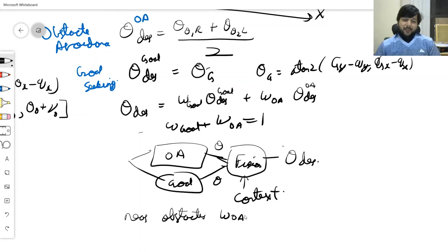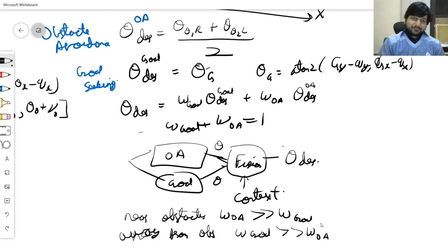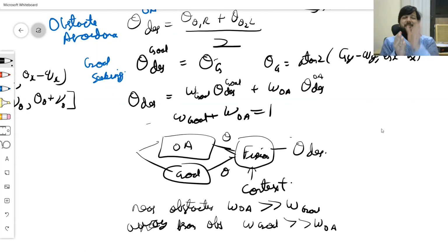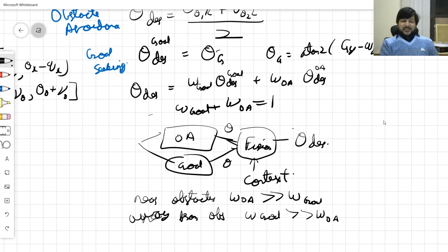I am more obstacle conscious, and away from obstacles, I am more towards go straight to the goal. So that's a fusion, and again, fusion you need to take care of. Sometimes two opposing behaviors, avoid this obstacle from the left, avoid this obstacle from the right, and you bang into the obstacle. Weighted addition. That's why as we go nearer to the obstacle, the goal will be gone, and first avoid the obstacle, we'll care about the goal later. So that's the one that gives me theta desired.